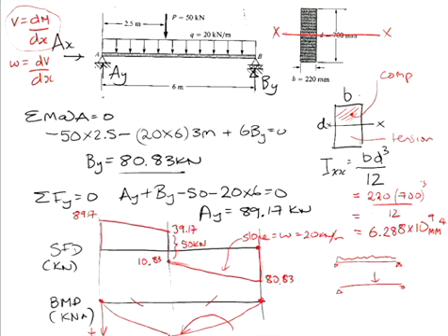So the most basic way is to therefore cut the beam at 2.5 metres and actually calculate the value of the moment there. But you guys don't like doing it the most basic way. You like doing it the quickest way, and that is to calculate that area in here. So hopefully you can all work out the area of a trapezoid. So it would be the average height,